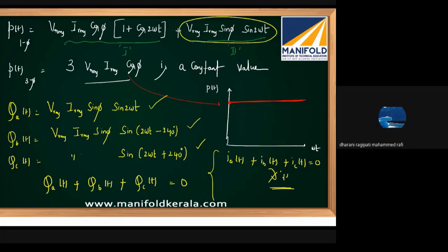Understand? Likewise, there is a reactive power flow in the network in all three phases, but however, the instantaneous sum of all three phase reactive powers is becoming zero. That's why this term is not showing the reactive component. Understand? Very, very important point. No textbooks will teach these points. I hope you are able to get it.